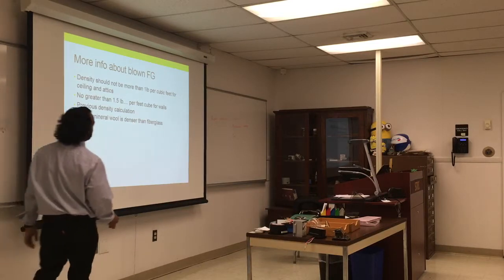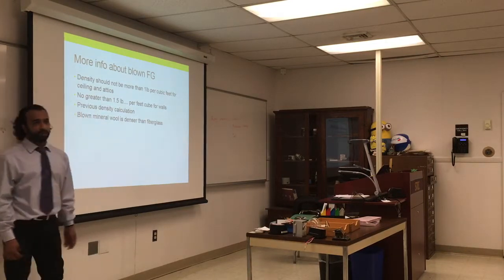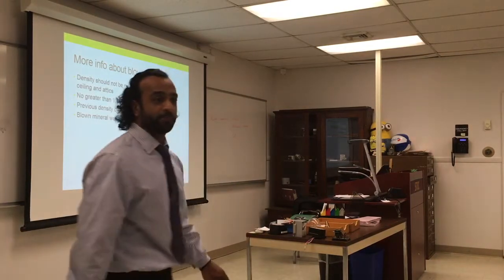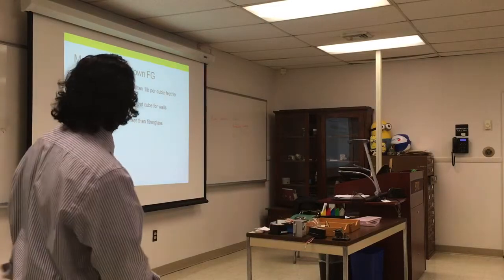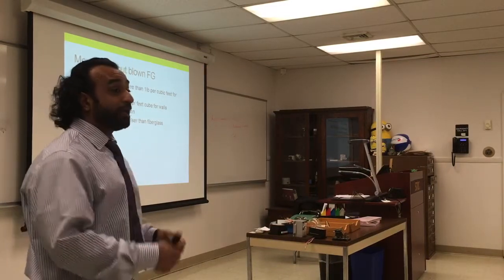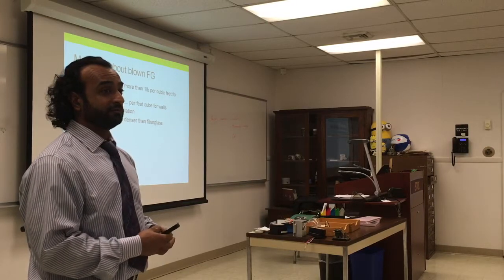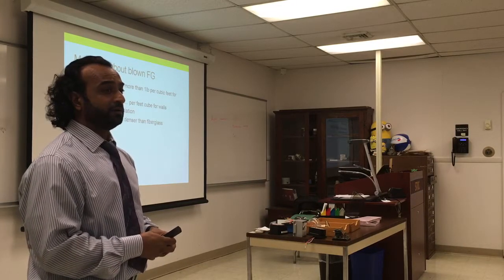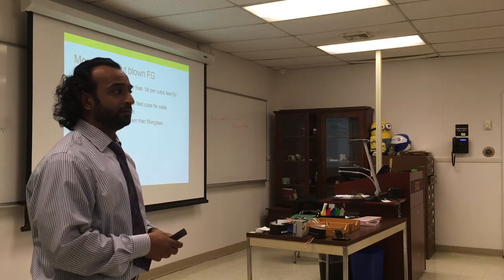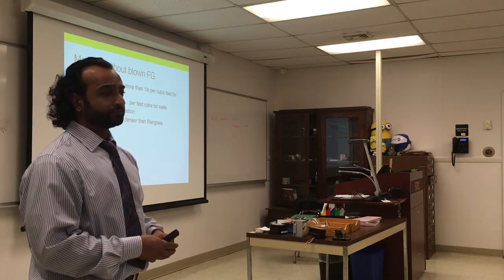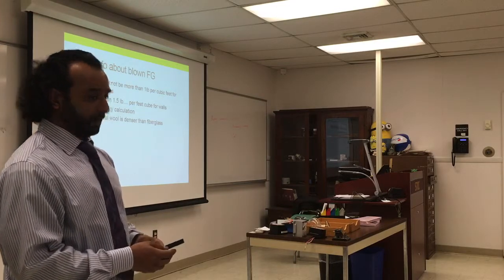Blown mineral wool is denser than fiberglass. Again, that's common knowledge. It's way more. Is that inside a wall? Yeah, that's a wall to the outside. Don't insulate walls from room to room. I just recently did a house where we had 4 inches of rock wool outside, and then 6 inches of rock wool inside.